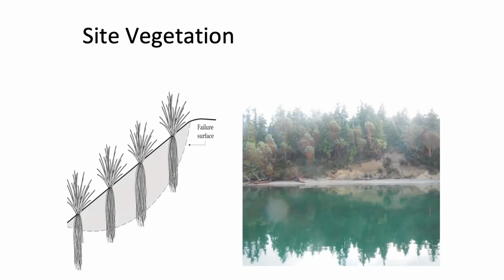So how would you determine the dominant fetch? A lot of times your drift direction is driven by that dominant fetch. The best way to check, if you have the availability, is to look at actual weather stations to see where your high winds come from and where your prevailing winds come from. Typically that will tell you exactly what your dominant fetch is.